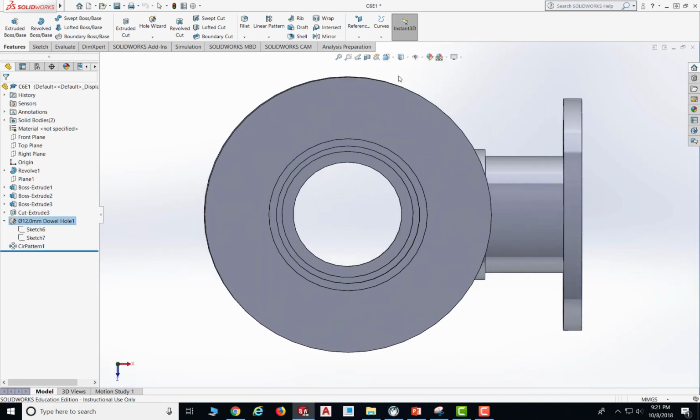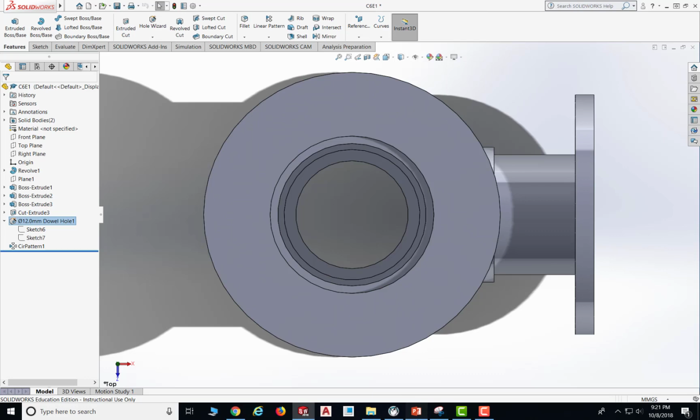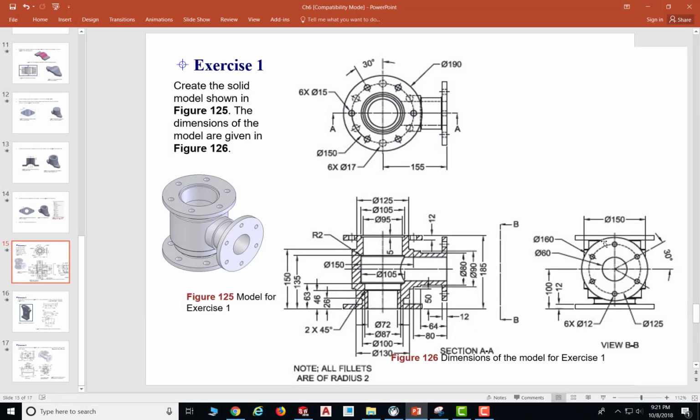So this is the top view. Now I am going to make these holes at the top. As you can see, they are slightly different. At the top, it's 60 degrees, as a solid line. But the bottom is 30 degrees, as a dashed line.